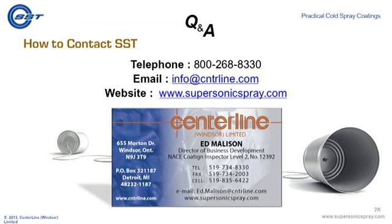The answer is no. Cold spray does not have the same degree of metallurgical bonding that welding does. And of course, in welding, you're going through some very serious heat and phase changes to get toward that metallurgical bond. For example, with welding, I can put two flat pieces of steel, butt joint them together, and weld together some web material that may be used in a structural beam or a bridge. So I'm actually joining those two structural materials with a weld bond. Just to be clear, cold spray is not meant to be used as a structural weld bonding of two structural materials.